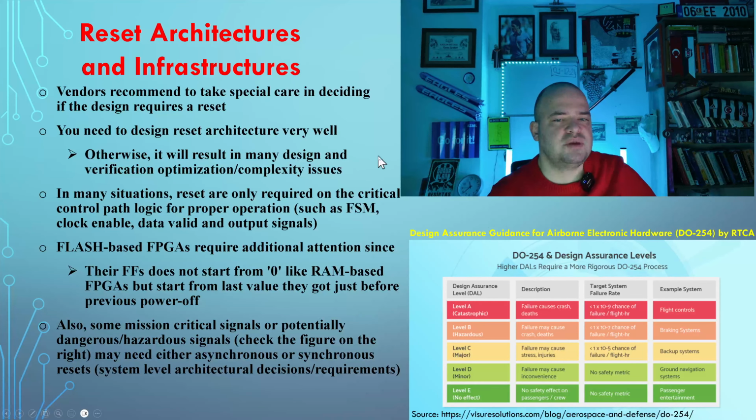Otherwise, your future colleagues that will be using your designs will be confused, and since maybe they don't have enough experience regarding that, they will add those signals into all of those resets under that reset statement, and they will waste some resources, or they will lose time considering why reset values are not provided for those signals.